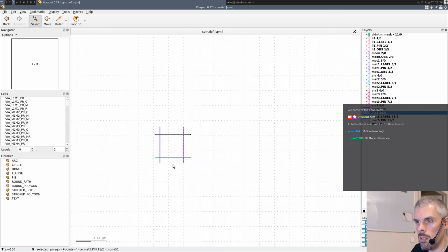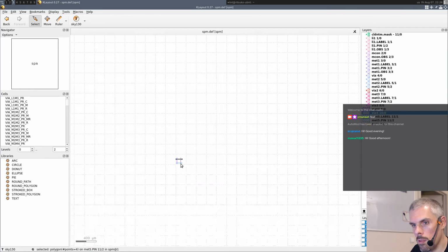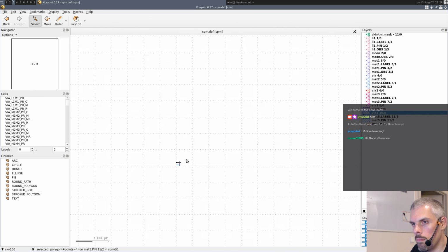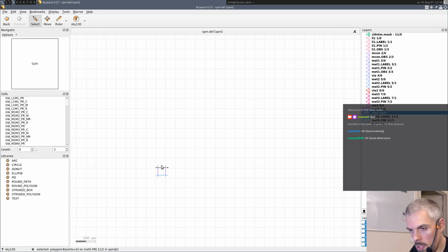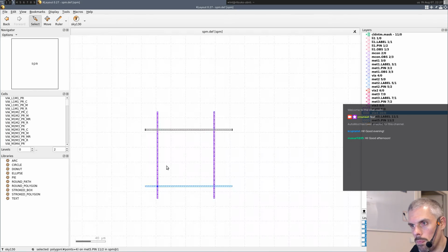But you have to imagine that your chip, I mean, this is 100 micrometers pretty much. The entire chip is going to be like 4mm by 4mm. So it'd be something like this, right? So you have an entire grid distributing the power all across the chip, to make sure that you have a low inductance path for all your power connections, basically.